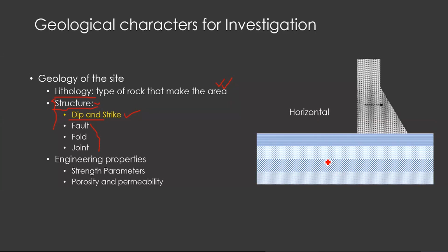Remember the forces which are going to act on this. The first one is the horizontal force exerted by the pressure of the water. The second one is the weight of the dam, acting vertically downward. So the effective force would be at an angle to these two forces. This is the direction where the force is going to apply. As a result, the contacts are going to have a force which is angular to the contact, so there will be a chance of shear failure.